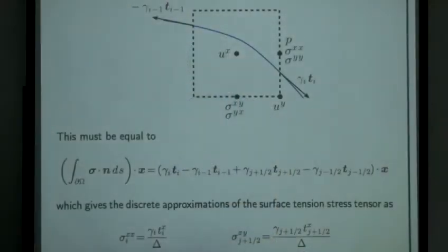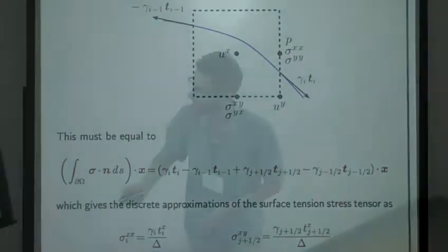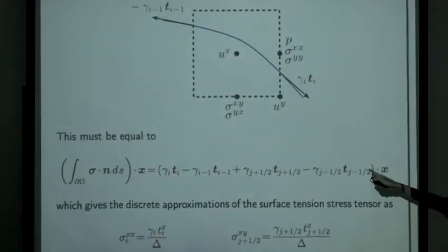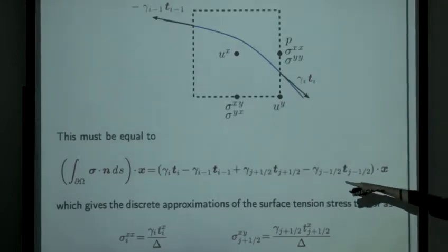So now how do you compute the stress tensor? What is the stress tensor? Well, I gave the solution earlier, right? There is a connection between the tangential forces that you have to sum and the stress tensor. The connection is easy: when you look at the sum of these two tangent terms, you are looking at the intersection of the interface with the side of the control volume, okay? Each of these intersections corresponds to the corresponding stress tensor term, which is exactly what I do here. So I write the general form for the intersection, okay?